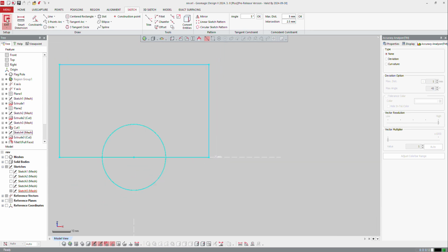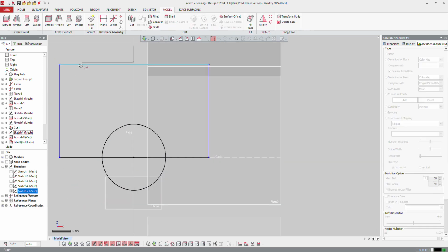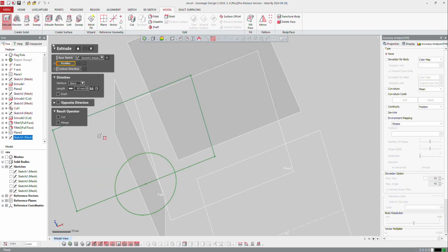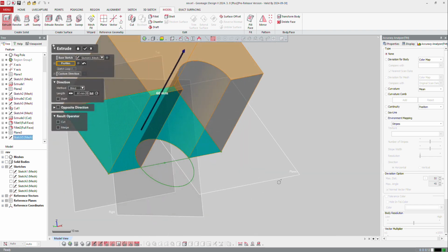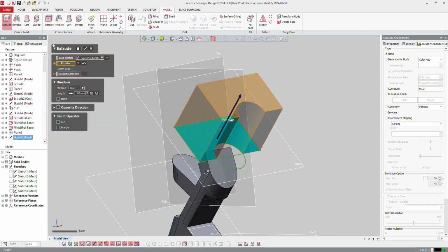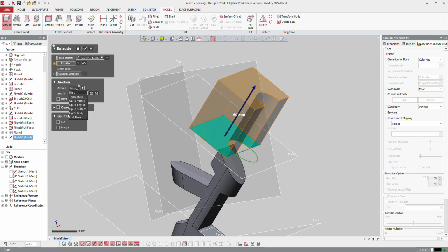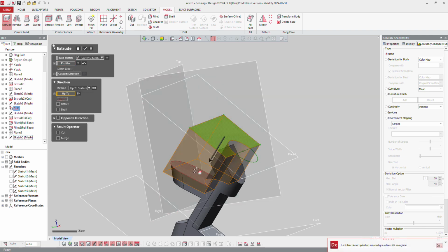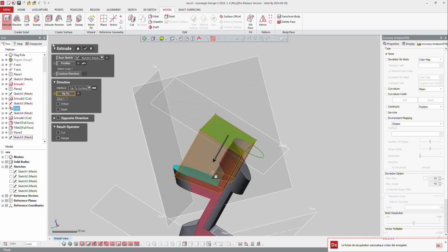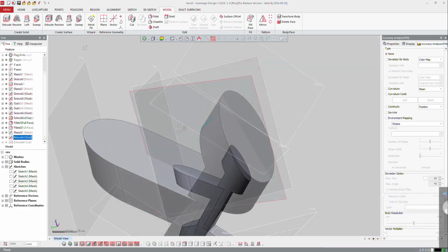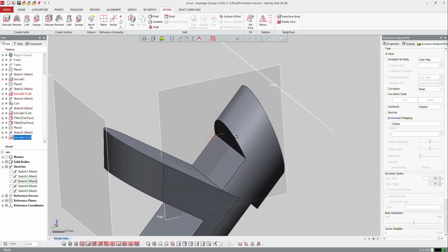It doesn't matter again. I can now right mouse click on this sketch, extrude in solid, that shape, Alt space to display my solid body, and ask the software to go up to a surface, which is going to be that one. So it's extruding up till it reached that area, and I cut the model. So you can see now it's a nice shape we get there.